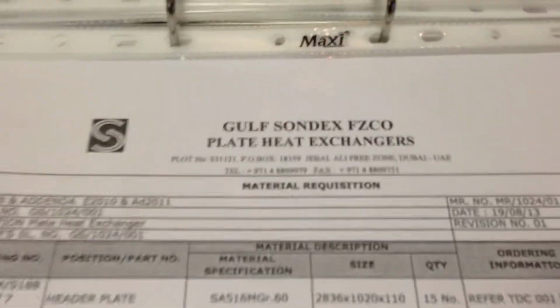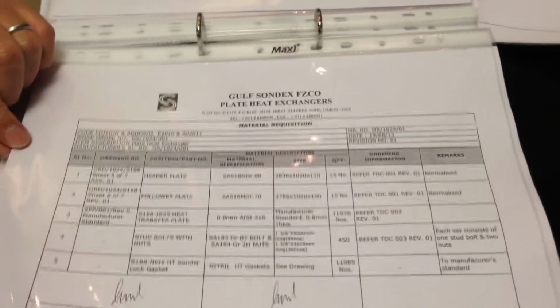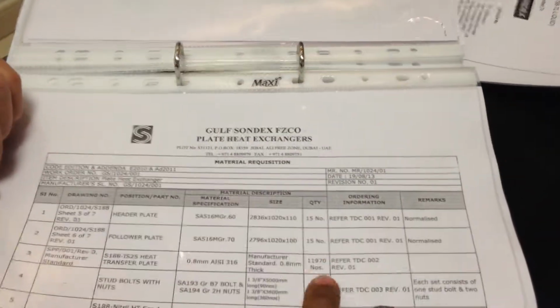And this is the material requisition. This is for our internal reference. We keep the material we are going to use, like the 1500 adjustment size, everything we have mentioned over here. And this is the technical delivery condition, how the materials will be. When we are ordering, the plate finish, what grade and size, like SA 516 grade 60 plates, it should be in normalized condition. And this quantity and size as per the PO we have done. And the MTR, we record the material test certificate. And for the material columbium or niobium, the heat analysis should be 0.05% as per the material requirements.